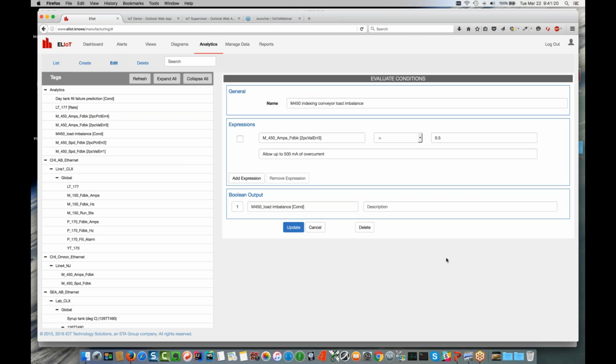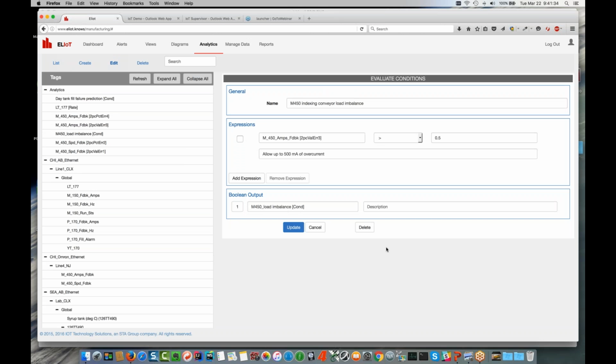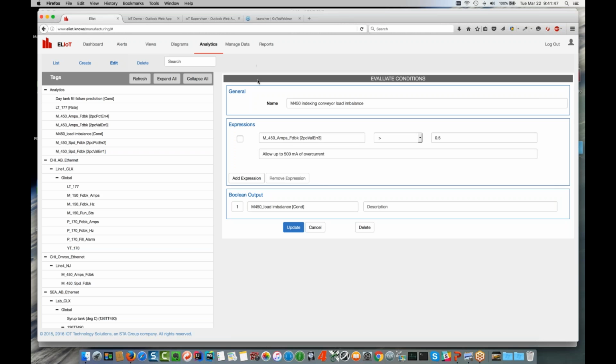So for example, if I expected 11 amps and I'm seeing 11.6 amps at 19 hertz, then that's going to trigger an error. And by the way, when that error happens, make this condition variable true. I've made this a simple one. You can imagine, something else we might check for is maybe we'd have an open winding. So I might also want to check for the current going down to 0 or less than a certain amount. I could have done that as well, but for the purposes of keeping the simulation simple, we didn't do that.